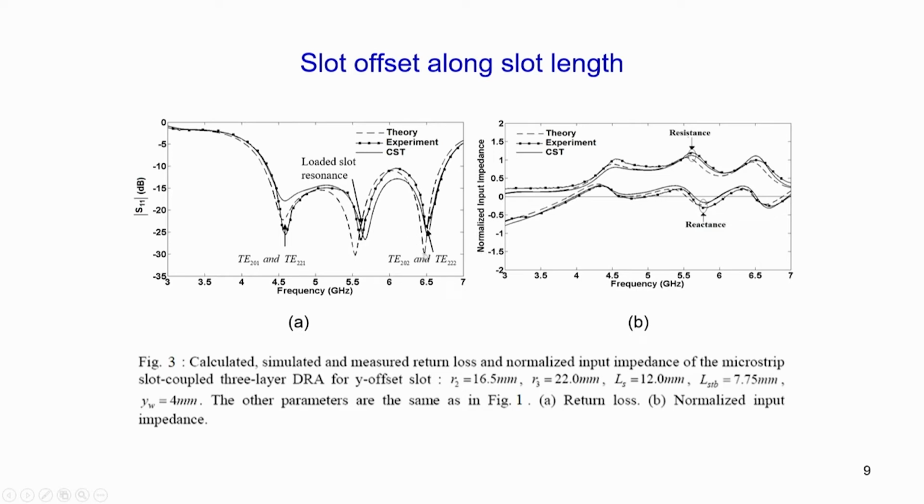The same happens at the third resonant frequency, at the third dip of S11. We have the third dip, which is contributed essentially by the third modal index. Here it is 1, here it is 2, and these two are again degenerate, TE202 and TE222, because N and P are the same, and here also the field distribution is potentially different because the value of the second modal index is different. Therefore, we have to see exactly how much TE202 and how much TE222 are excited, and whether they interfere with each other's pattern. Okay. So, we have to be concerned about that.